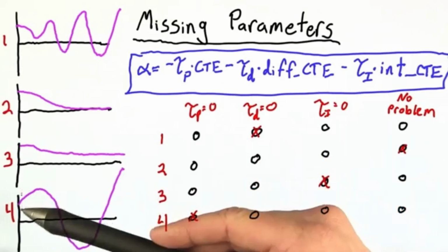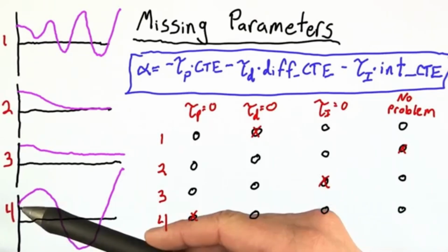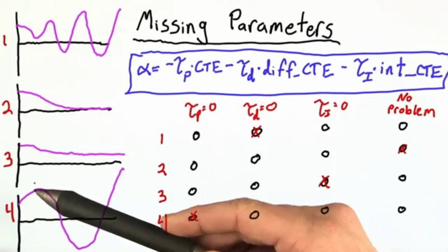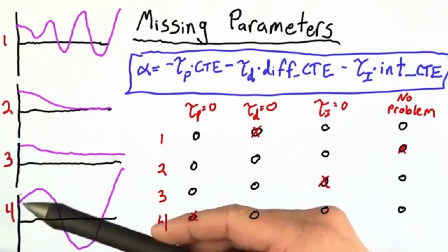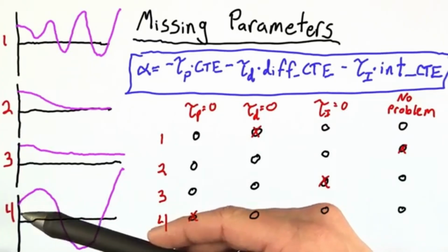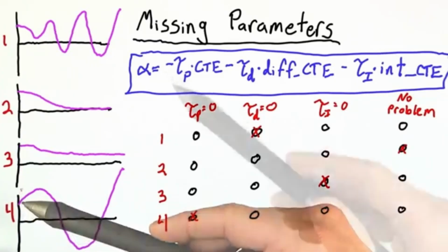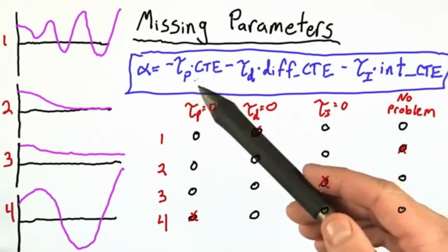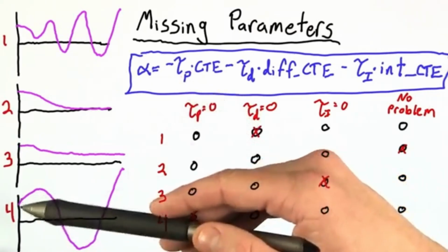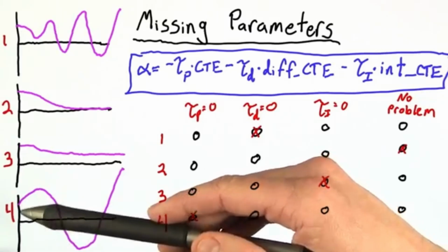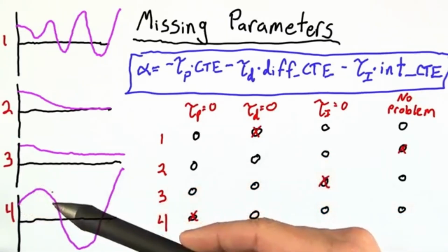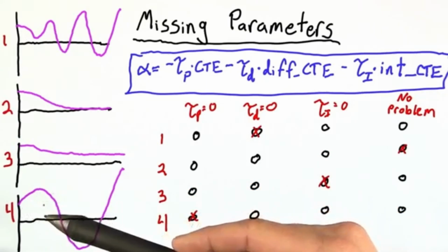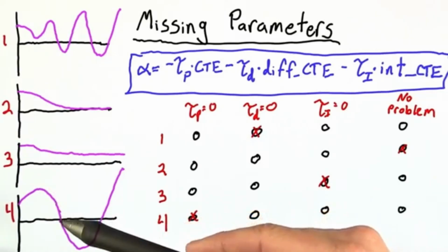The key to understanding number 4 was realizing that the robot starts by moving upwards. This is the only case where the robot started going up. And what's happening here is the drift is dominating. Since tau p is equal to 0, there's no initial term that steers the robot towards the goal. And without that, the drift is going to take over. Of course, as we accumulate error, that gets corrected for and we steer down.